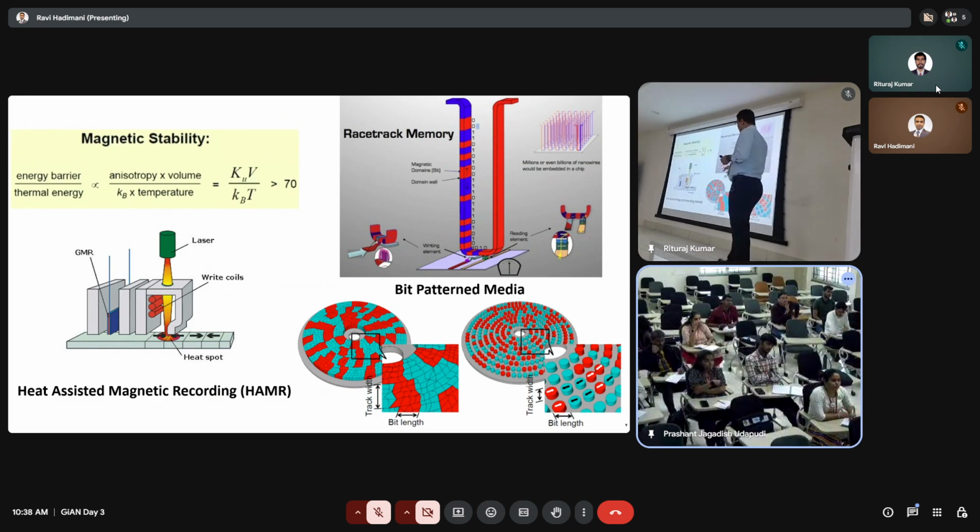heat-assisted magnetic recording. Either this could be laser, or people have also used microwave, but the laser one became more popular. It's commercially more feasible. They exist in the market nowadays. Heat-assisted magnetic recording. Okay, so we have already reached the saturation magnetization. That means write heads can't improve anymore. If you can make a write head that can have saturation magnetization above 2.4 Tesla, you can be an instantaneous millionaire. So a lot of people have worked on it. So that is the frontier now.